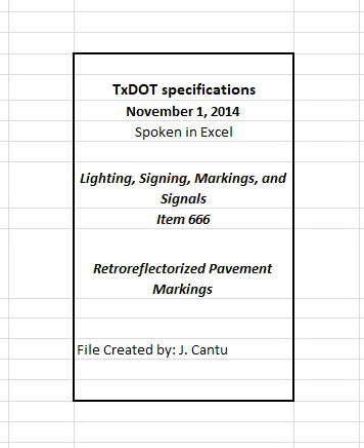Restripe at the contractor's expense with a minimum of 0.060 inches, 60 mils, of Type 1 marking if the marking fails retroreflectivity requirements. Take measurements every 0.1 miles a minimum of 10 days after the second application within that mile segment for that series of markings. If the markings do not meet minimum retroreflectivity after 10 days of this second application, the engineer may require removal of all existing markings, a new application as initially specified, and a repeat of the application process until minimum retroreflectivity requirements are met.